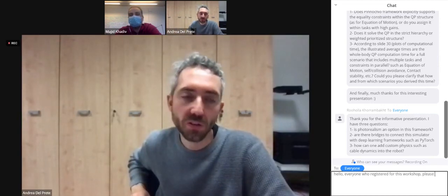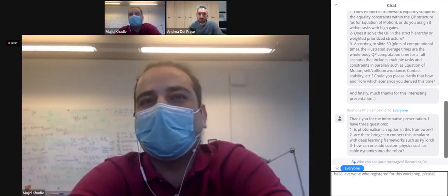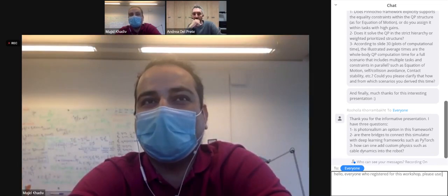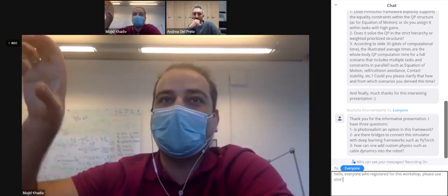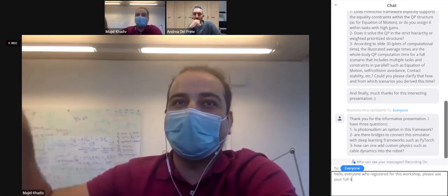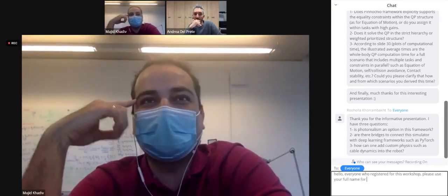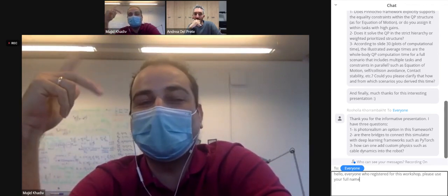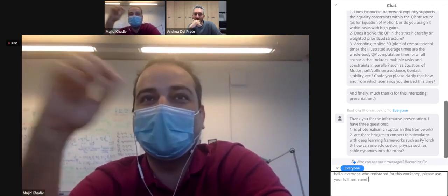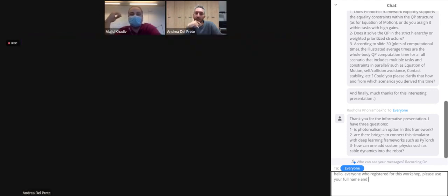We should just remove the friction cone constraints, basically. But there might be some bilateral contacts that have friction cone. For instance, a hand grabbing a pipe. Then you have one directional friction constraint. So I think it's not a very trivial problem. Depending on the degrees of freedom of motion, you can have different types of bilateral contacts.